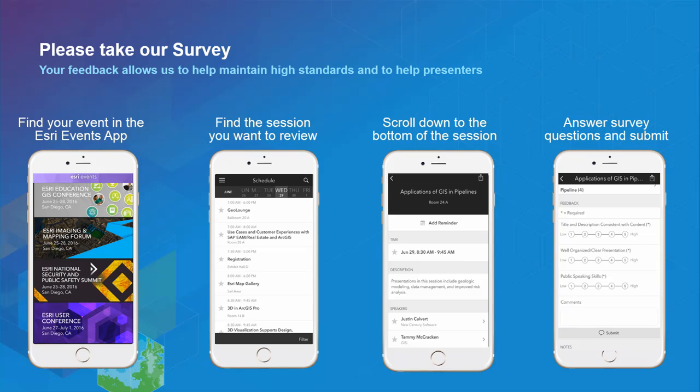Okay, so the question is, what determines the order of draw for polygons when they have outlines? By default, feature order is determined by what's returned from the database. So if you have two polygons next to each other, whichever one gets returned first draws underneath the next one. So you put them in there twice, and you do a selection query on one set, and put in a copy of the other, so you draw it twice. That's how I resolve it.